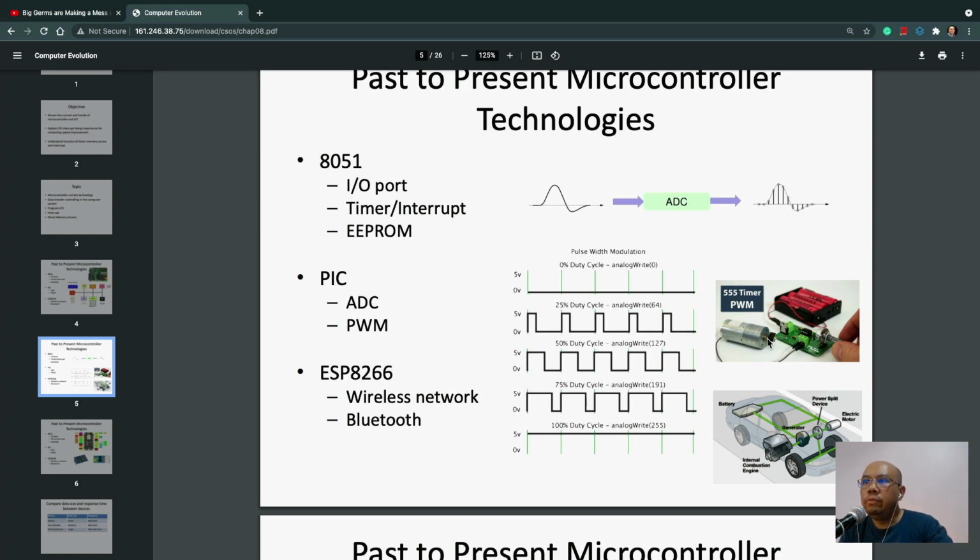So when we use the motor at low speed and need the torque of the motor, you need to supply the motor with a pulse signal. That means you turn on and turn off in a very short time and send it to the motor.